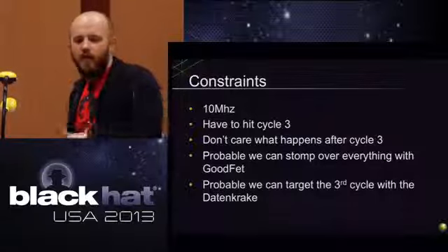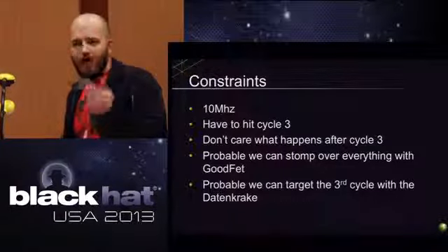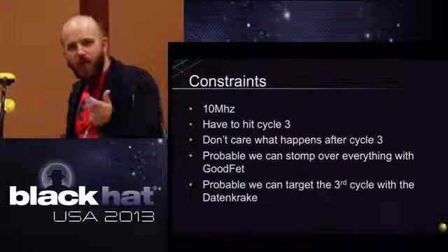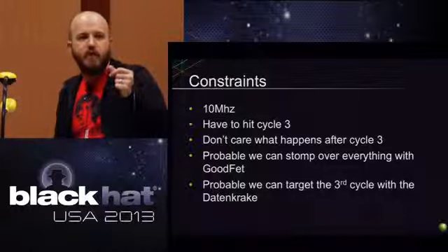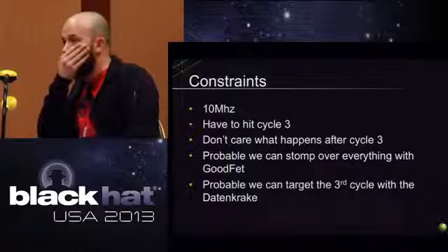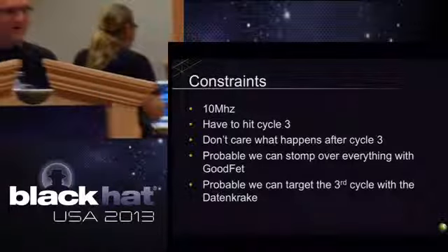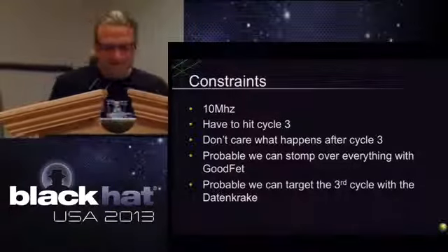So as long as the thing doesn't constantly go into a reboot loop, for example, and if you can get past that long enough to keep it alive long enough to let the debug interface be up, then you'd be able to halt execution, and at that point, you've got the debug interface. Which is something he reminded me of, because I was focused on that clock cycle 3 and was killing myself, and then he was like, dude, you don't have to hit it. And it got a little easier.